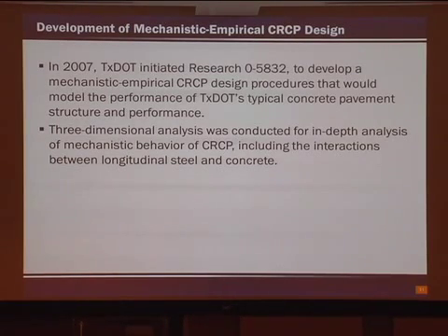So in 2007, TxDOT started our own research project to develop the ME design procedure that would model the performance of Texas concrete pavement. A 3D finite element program was conducted for the CRCP performance, also including the interaction between the longitudinal steel and the concrete.